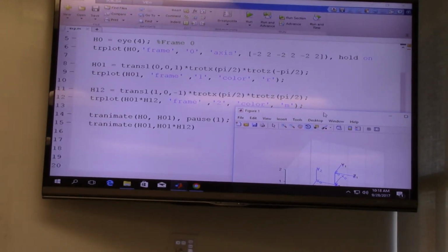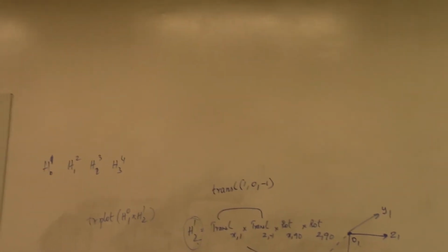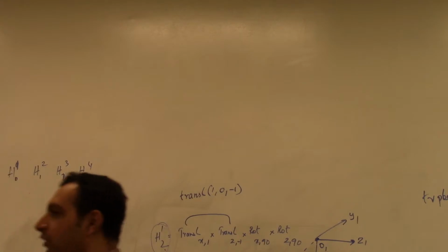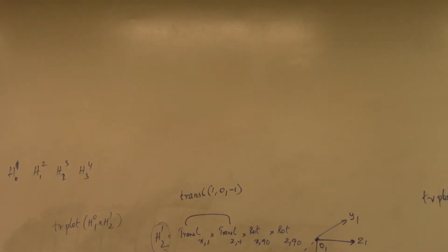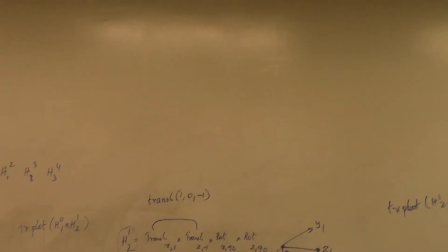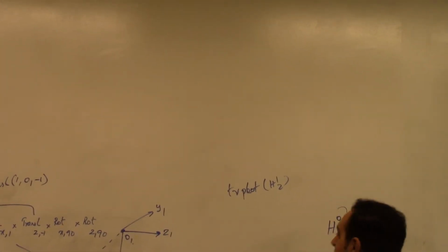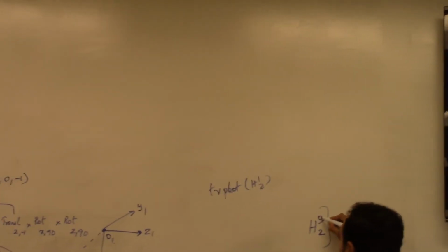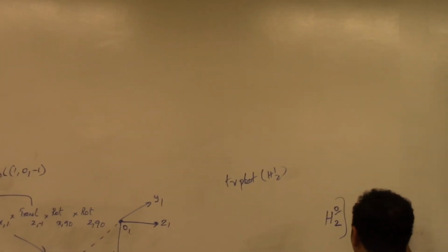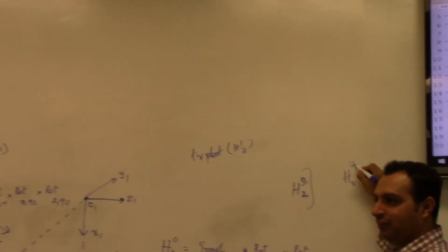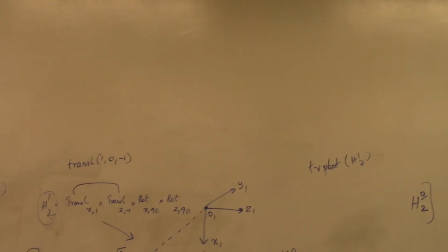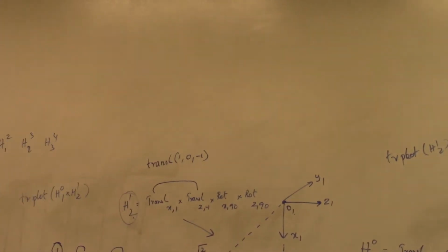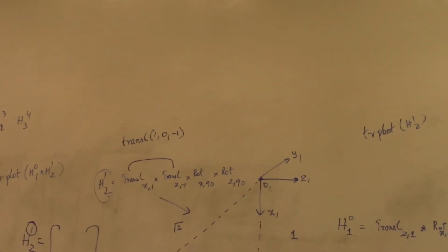to 2. So let me tell you, okay, if I tell you, tell me my location with respect to New York, right? Then New York is the reference, right? I'm referencing myself with respect to New York, right? So if I tell you, what is the translation or what is the homogeneous transform of this frame with respect to the base frame? Okay, base frame is the reference. Okay, so with respect to the base frame, it will be like this. If I write it like this, 2 is the reference and I'm moving from 2 to 0. Okay, with respect to which frame you're doing this, that frame will be your reference frame. Okay, you're relating yourself to that frame.